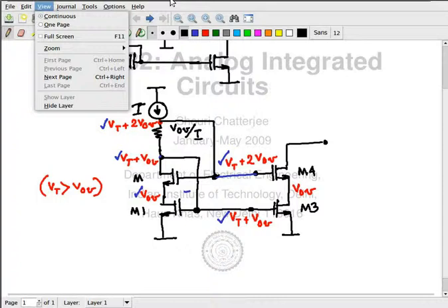Does that answer your question, kind of? It doesn't, I know. We won't make a reference current source to start with. We'll make a reference voltage source, a band gap voltage reference source, and from there we generate the current source. Later on we'll do this. We need an Opamp to do it. So I have discussed the Opamp.